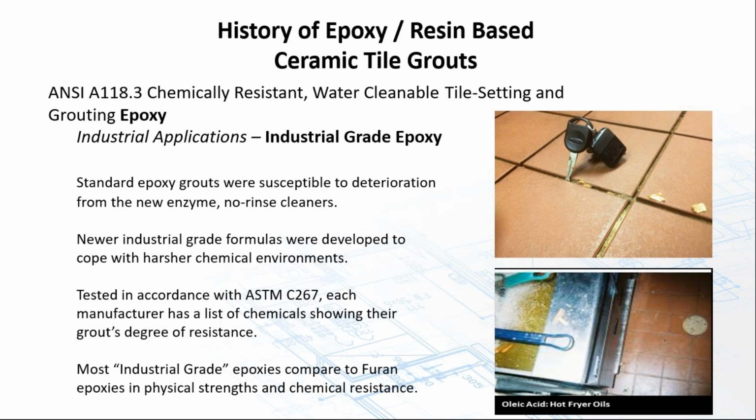If you're doing a commercial kitchen, as a design team, as an architect, you don't know how the owner is going to clean it later on down the road. You don't know what products they're going to be using. We highly recommend that you stay with an industrial grade epoxy grout for that back of the house, for that kitchen. They are limited in colors. You don't see the wide range of colors with it, but these are grouts that will hold up and perform the way that your owner expects, and give you the life expectancy out of that back of the house, that kitchen floor, that industrial floor. Keep that in mind when you go into the specification.